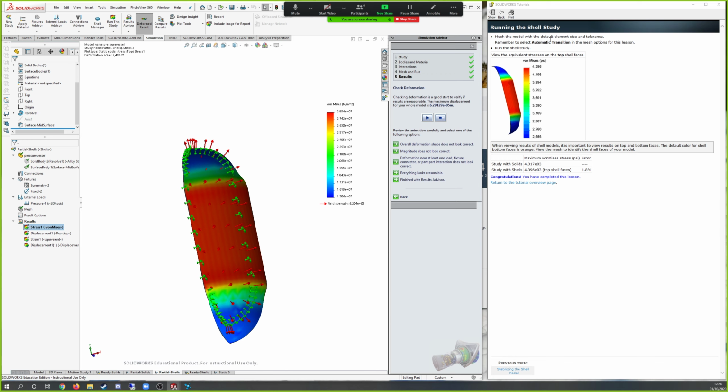So what it does, I'm going to draw on your screen, James. Yeah, go for it. You've got a tetrahedron, right? These have nodes at every corner. And if it's a second order element, you've got nodes along each edge. You end up with 10 nodes.